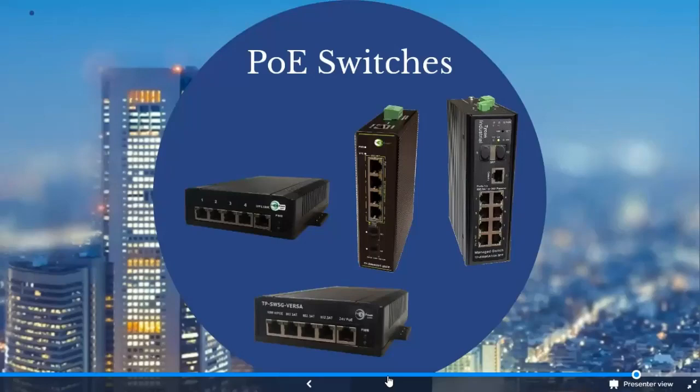Now, we also have the managed. We have a 4 and 8 port option. They do require 48 volt DC input to be able to access PoE out, but these will be on 802.3 AT output, as well as we just released 2 new switches, both 8 ports. One will give you 24 volt PoE or 48 volt PoE at 802.3 AT. So you're able to configure based on what your needs are.